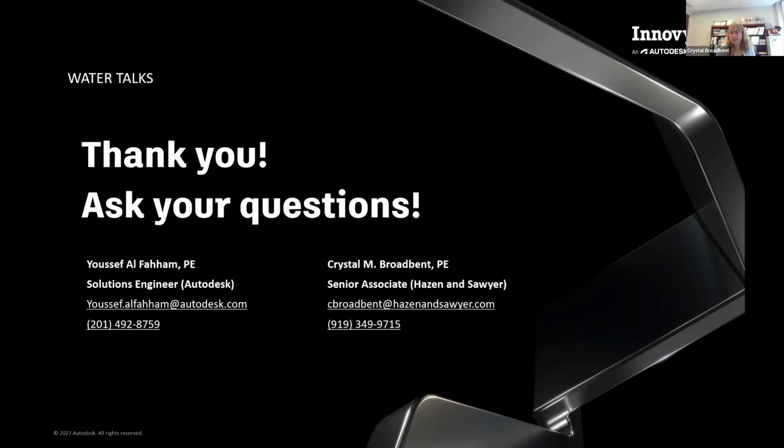existing compressor tanks or bladder tanks, obviously the one you probably know mostly is just the volume of the tank, right? What you may not know is how they are operating it day in and day out. Especially for compressor tanks, there's a level range. In the model, you don't put the level range. In the model, you put the initial gas volume. And that initial gas volume is usually the ideal level of the compressor tank.